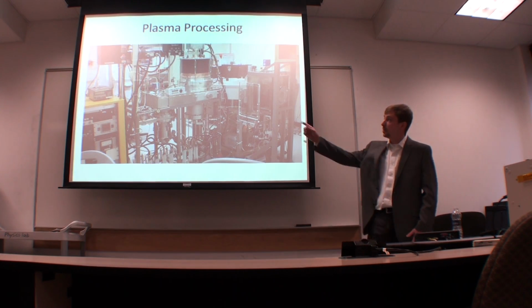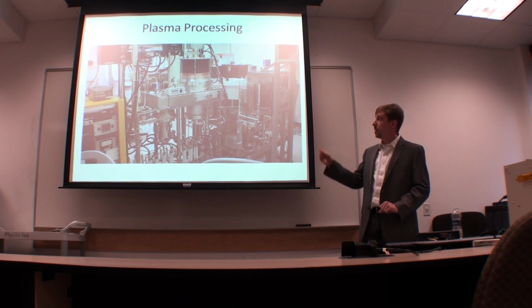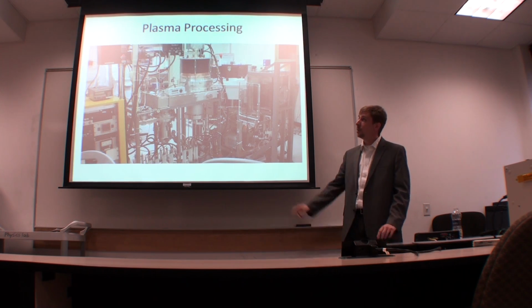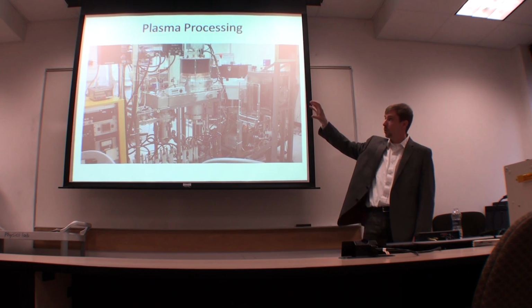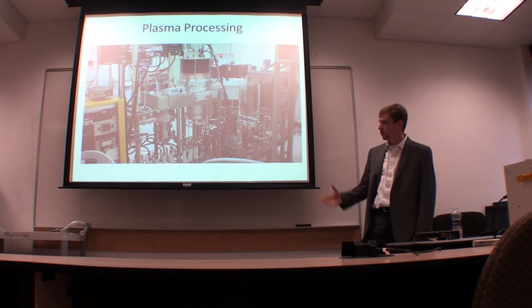And you can see here is a large magnet to hold the plasma gas. There's a robotic arm and some actuators that were used to move the silicon wafers into the machine. Up on the top there is the microwave radiation source, which is directed into the plasma. And you can see various pneumatics and cooling systems and exhaust systems.